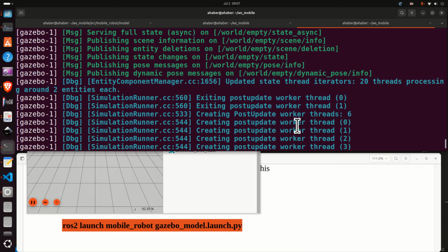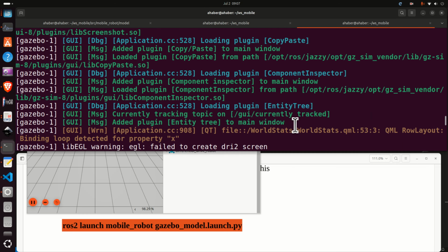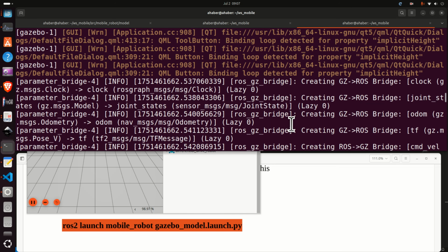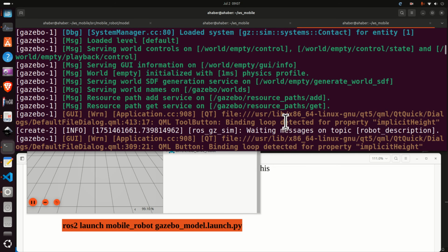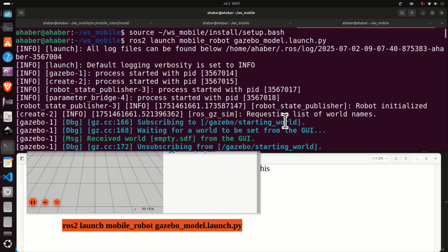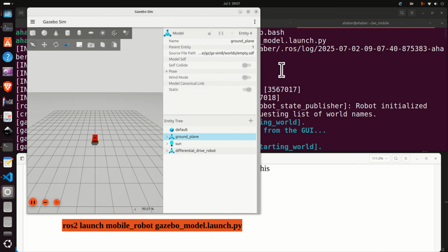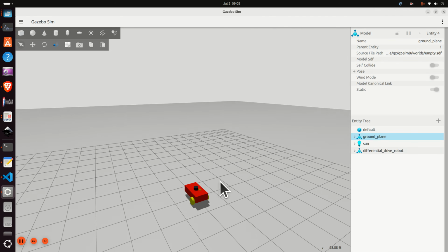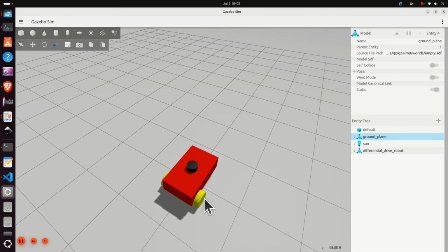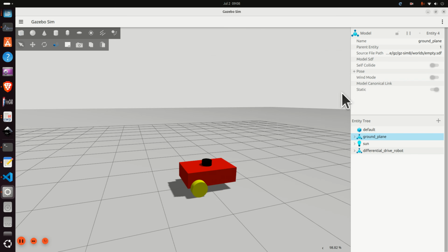Now it's still a good idea to go back and analyze whether there are some warnings or some errors over here. Currently, I don't see any specific errors, maybe a few warnings. However, here's our simulation. Here it is. Beautiful. Looks beautiful. Next, let's explain how to visualize our Lidar. So click over here and search for Lidar or visualize Lidar. Click here and you will see the menu here.